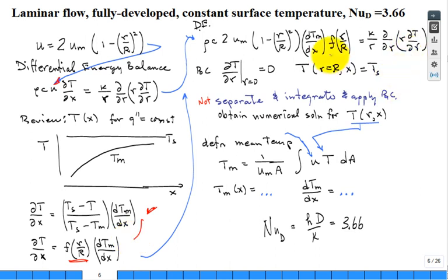Setting it up, you have this function and then dT/dx. You come in, you separate, integrate, you remind yourself of the mean temperature. I'd use a couple of dots here and a couple of dots there, because you can get it, and the book has that description here. And you equate the global energy conservation statement with your solution to the temperature profile, and you look to package up a Nusselt number, and it comes in 3.66. If it was a grad class, maybe we'd spend the whole day on it. But in the interest of time, we press forward.